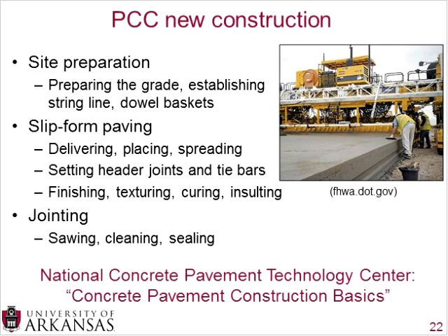And you also need to place your dowel baskets down. The dowel bars are used for load transfer between the slabs of concrete or any sort of reinforcing, but you want to make sure to get all that steel in place before you start the paving. And PCC construction generally uses a slip form paver. There has been some work done with roller compacted concrete, but again, that's one of those newer technologies that we won't be going over today.